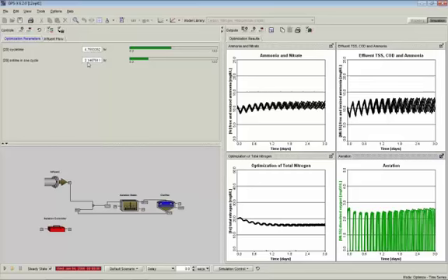So you can imagine that if I had a different set of parameters up here, if I had a plug flow tank and I wanted to do the split of the aeration, or if I had a dynamic event where I wanted to do some step feeding and I didn't know what the fraction should be, I could get that done through the optimizer. I've seen it used in a number of different ways, particularly for settings where you have parameters that are maybe not intuitively connected to each other, and you want to know how one is going to affect the other, you know, recycle rate and aeration distribution and so on.